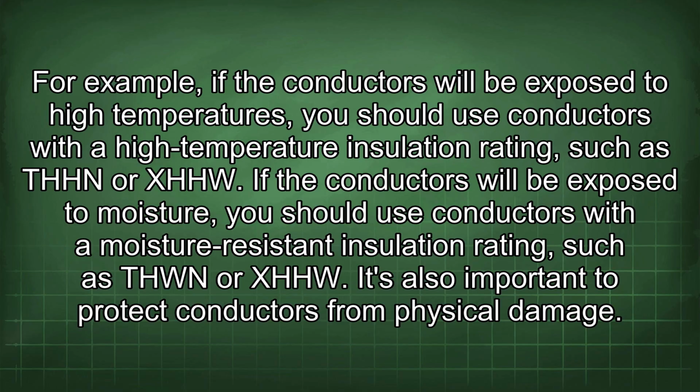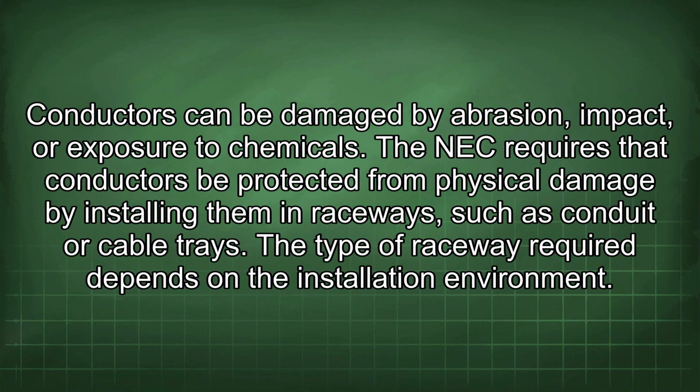If the conductors will be exposed to moisture, you should use conductors with a moisture-resistant insulation rating such as THWN or XHHW. It's also important to protect conductors from physical damage. Conductors can be damaged by abrasion, impact, or exposure to chemicals.